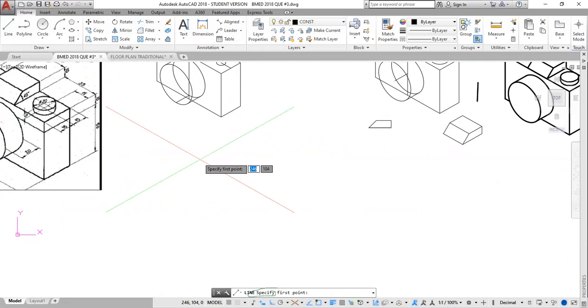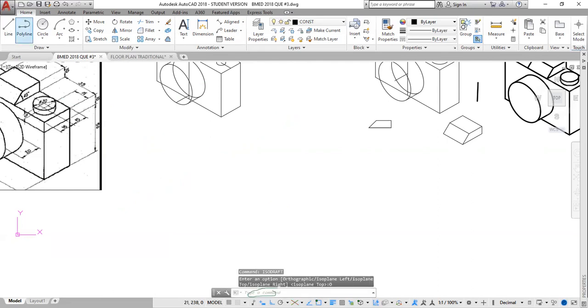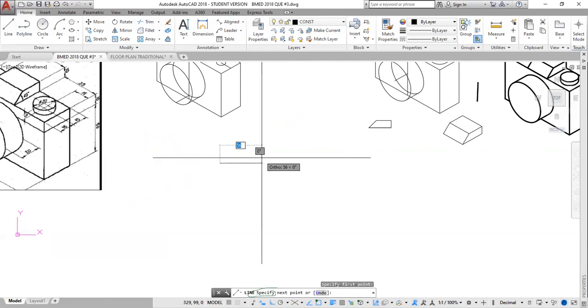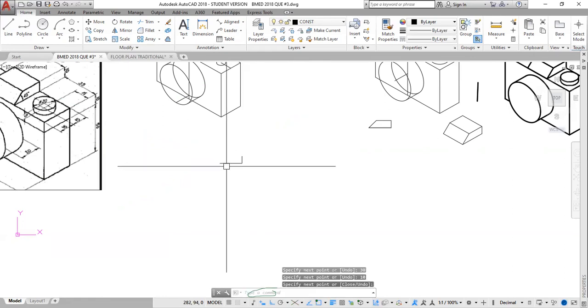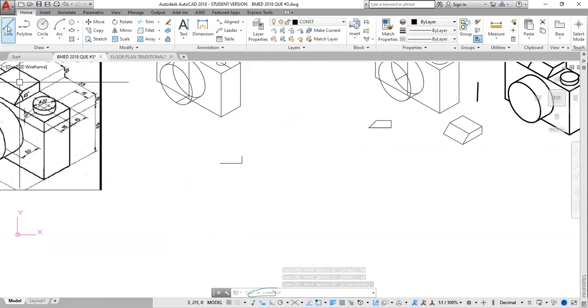I draw this in orthographic mode. So for that, you must change back to your regular drawing plane. So ISODRAFT, type ISODRAFT, enter, orthogonal mode, and then we draw a line. One here, 30, 3, 0, enter, up, 10, 1, 0, enter, enter. Then I draw a line at 45-degree angle.